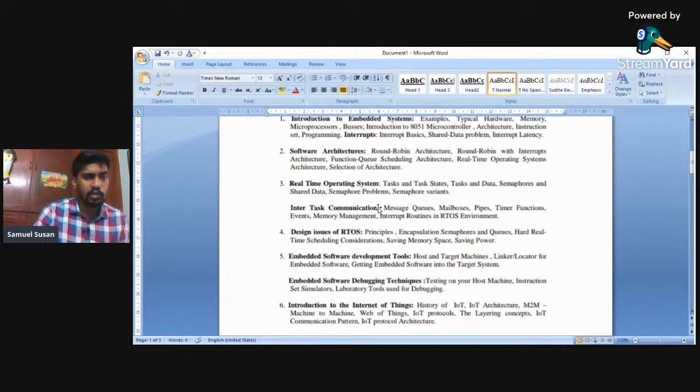You can see the difference between a processor and a controller. We call the microprocessor simply a processor on a chip. It is a small processor which contains a control unit, arithmetic logic unit, and memory unit, connected using an address bus, control bus, and data bus. It can read the data, do some processing and give us the output. But it requires peripheral devices, which you might have studied in the microprocessor subject, like 8255, 8259, 8251, 8253, and 8279, which are used for providing timing, handling interrupts, and other operations for interfacing other devices.